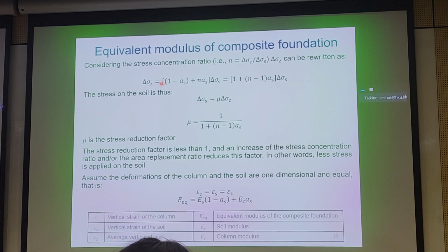And these, of course, are just more information, bonus material for you if you want to understand how to look at deep replacement. For me, I'm happy if you understand that there's two types of methods, excavation and replacement, and the various types of methods like dry and wet top feeding. The worst case scenario is I asked you what's the difference between vibro displacement and vibro compaction, something like that. Conceptually, for this module, we won't have to worry about any unit cell or stress calculations.